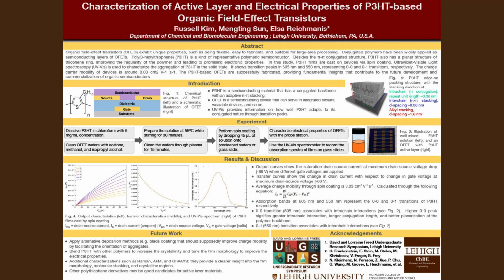it semiconductive. On the other hand, OFET is an organic semiconductor device made of 4 layers: the substrate on the bottom, covered by the gate dielectric layers, and finally, the source and drain electrodes. OFETs are rising in popularity because of the demands in biocompatible sensors, easy fabrication, and large-scale processing. Our OFETs are made at Lehigh in an ISO 5 cleanroom. As a note, the molecular structure of P3HT and a schematic of OFET can be found in Figure 1.